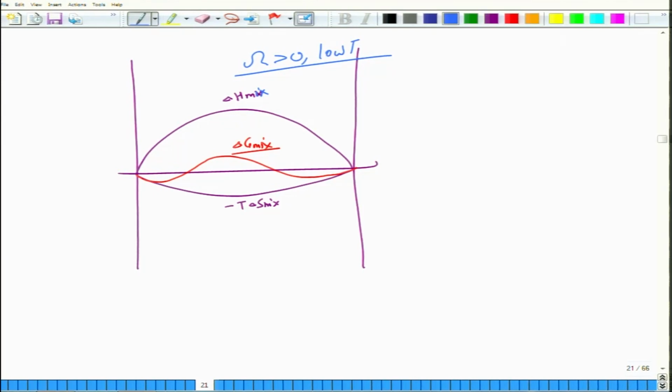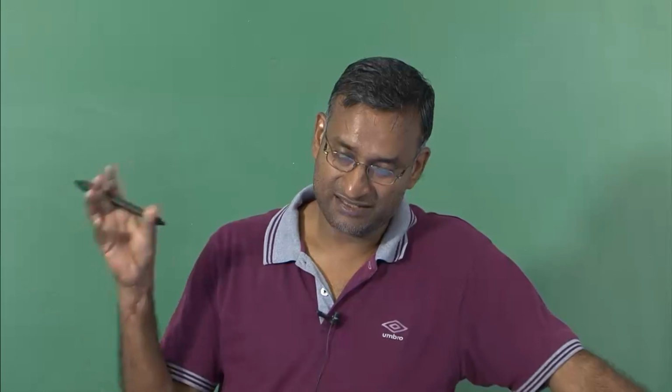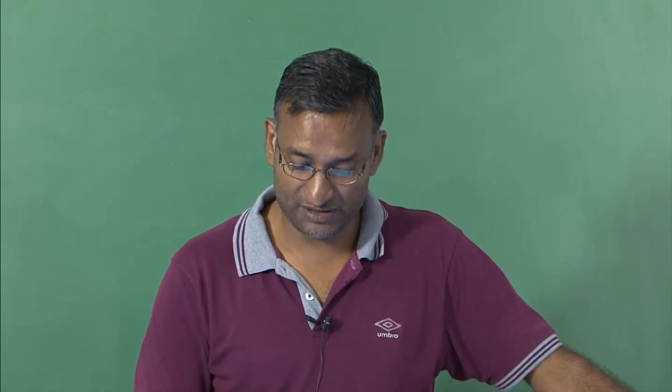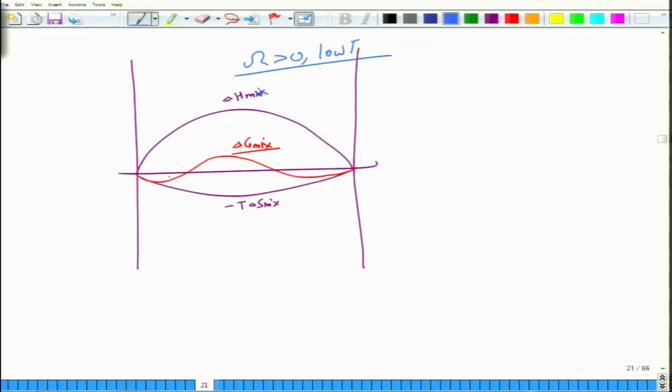So, this tells a very important conclusion that even a slight addition of impurity tends to lower the free energy of an otherwise pure material, and as a result the impure solid is thermodynamically stable as compared to the pure solid. This happens because the minus T delta S mix contribution prevails at lower impurity levels as compared to that at higher impurity levels.